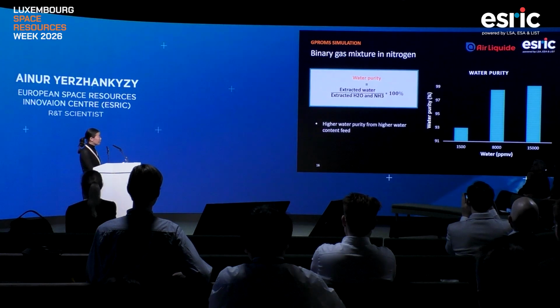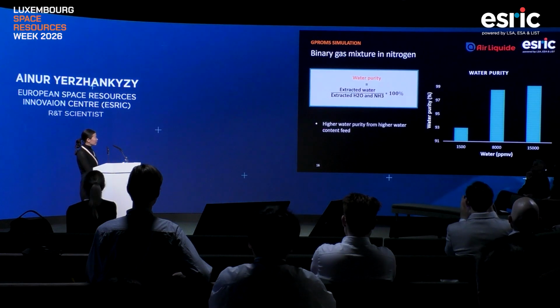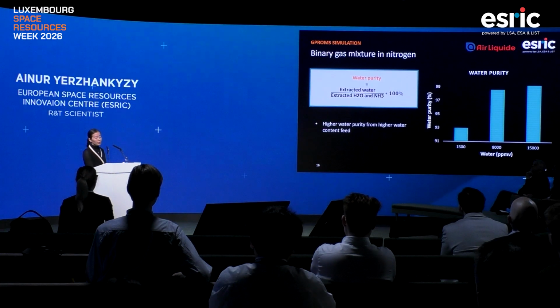In terms of purity, we observed that we can achieve higher water purity when we have higher water content in the feed, which is kind of logical because we have more water. But what we were initially expecting is that the simulation should have shown us higher purity when we wait until the full breakthrough. This means our gPROMS simulation still needs some adjustment, and this is work in progress.